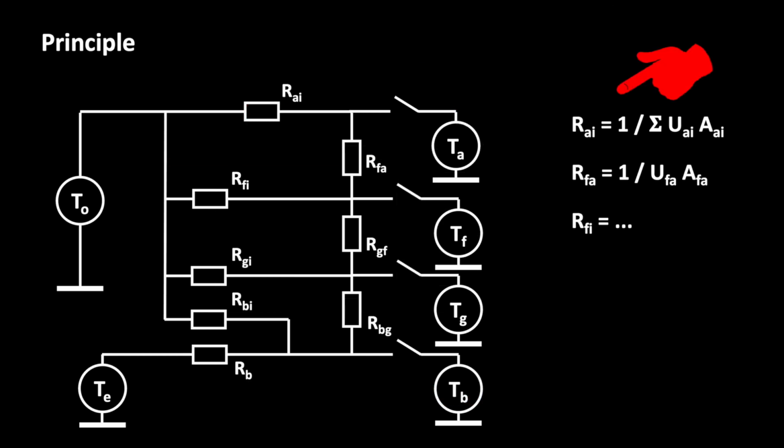With the so-called mesh current method, all voltage differences and currents in such a network can be calculated. The same can now be done with the thermal energy flows and the temperature differences. For this, you need the so-called mesh impedance matrix, which you can then apply like an extended Ohm's law. Okay, we will see that in a minute.